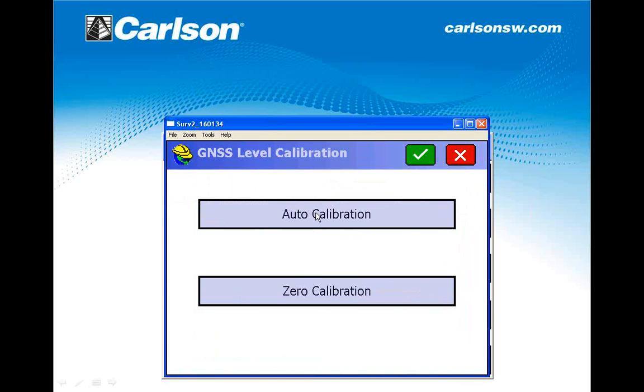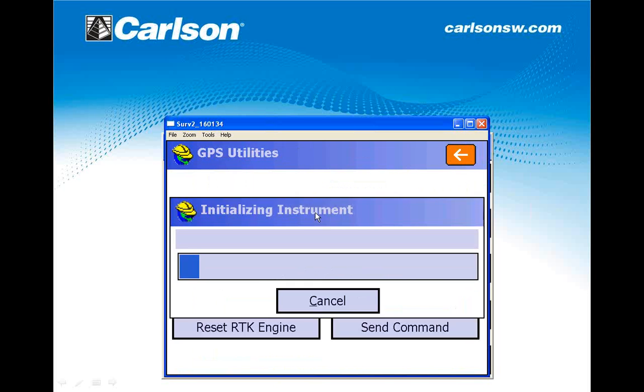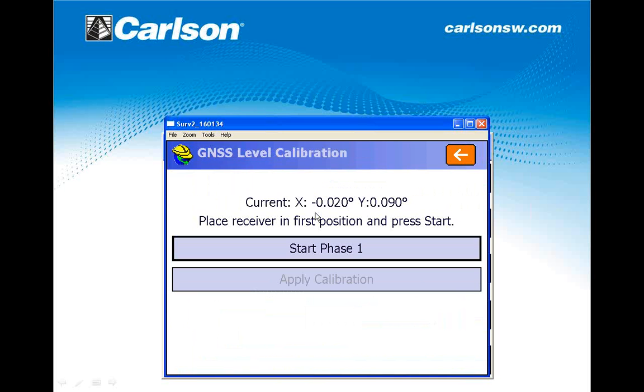So we're probably hiding and showing only the auto calibration. The auto calibration you could do on a tri-brush, or you could do on a pole. I suggest to use the same pole that you are using in the field, and you know how to calibrate a vial in the pole, like holding against a corner or something almost vertical and twisting 180 degrees. So this is more or less the process.